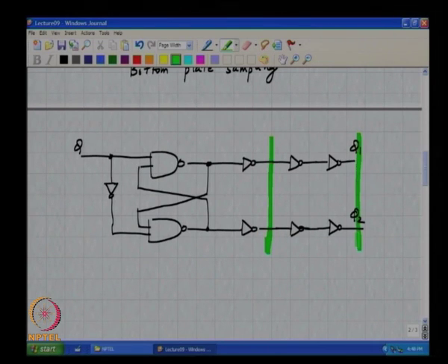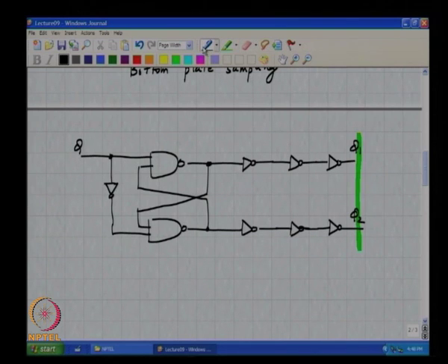So, these two are non overlapping too. So, obviously, it is impossible to advance a clock, I mean you can't advance a signal, you can only delay it, right. But if you call this phi 1, it is not as if you derive phi 1 a from phi 1, you derive phi 1 from phi 1 a, you understand. So, you can call this phi 1 a and phi 2 a, both are advanced versions of phi 1 and phi 2, okay.